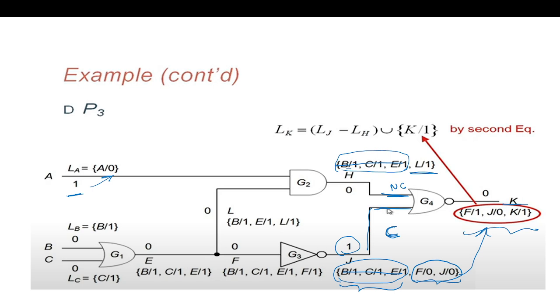So from this concurrent simulation, in one go, we have a pattern 100, so it can detect 3 faults. Previously, if we wanted to do a serial fault simulation, we needed one golden simulation. Next, we could have taken this pattern and simulated across this complete fault list of 3 faults, and then identified that these 3 faults are going to be detected by this pattern. But in this simulation, in one simulation, we got to identify that this is the pattern, and these 3 faults can be detected. This is the deductive fault simulation.